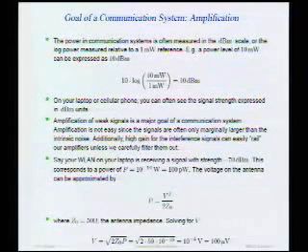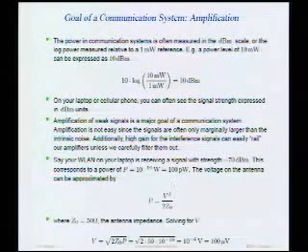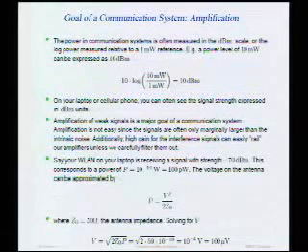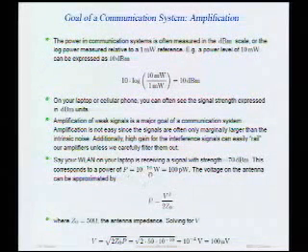Now, it's good to know that because almost all the communication equipment that you carry around with you, perhaps even today, has a little signal strength indicator, which is an estimate of how strong the signal is that's coming in. And if you look at your wireless LAN, you might find that a typical signal strength might be minus, let's say, 70 dBm. So if we take minus 70 dBm and translate that into watts, well, that's 10 to the minus 10 watts, or 100 picowatts. It's not much power, is it?